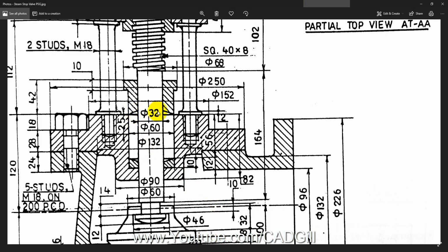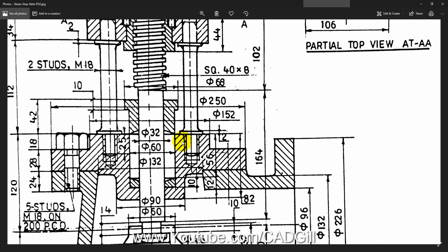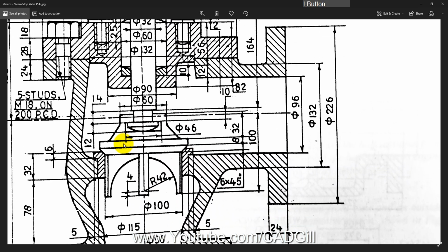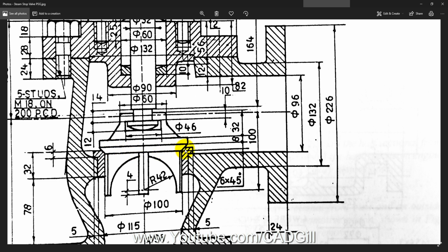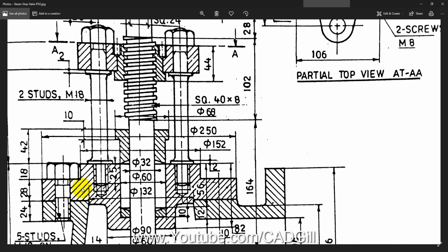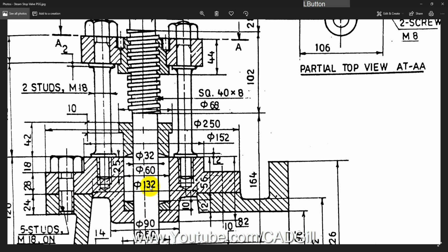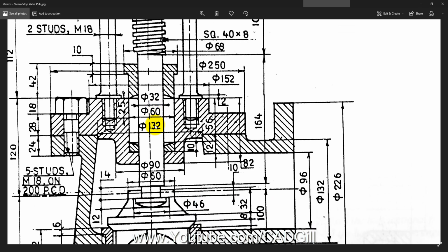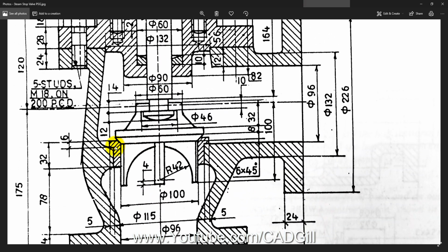You can see that there is some kind of cavity here, but this is only for your reference, so that you can see it, but there is no gap here. These kind of things happen a lot of times in drawings. So for example, here you cannot see any hatching here. So this part here is complete. Next, we have to decide which part we have to model next. Let's make this valve seat here first, and then we can make this valve easily.